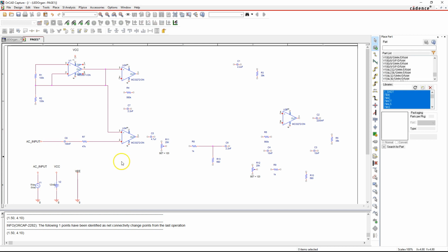Next, let's go with VEE. So I'll probably just move this text out the way a bit. Hit Control C to copy that and then paste it. So why do we need these two voltages, VEE and VCC? Well, it's because the operational amplifiers operate on power, and the power needs to have, for this particular op amp, negative and positive same magnitude. So we'll just wire that up.